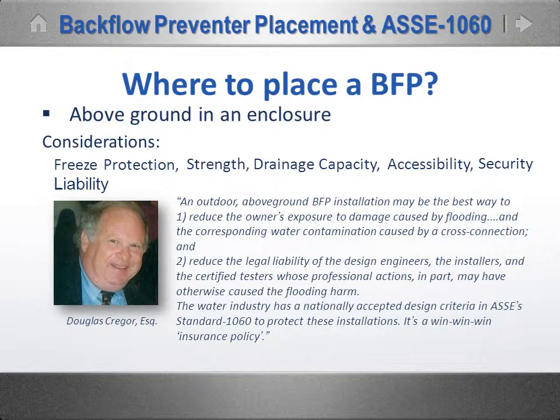He said an outdoor above-ground backflow preventer installation may be the best way to 1. Reduce the owner's exposure to damage caused by flooding and the corresponding water contamination caused by a cross-connection, and 2. Reduce the legal liability of the design engineers, the installers, and the certified testers whose professional actions in part may have otherwise caused the flooding harm. The water industry has a nationally accepted design criteria in ASSE 1060 to protect these installations. It's a win-win-win insurance policy.